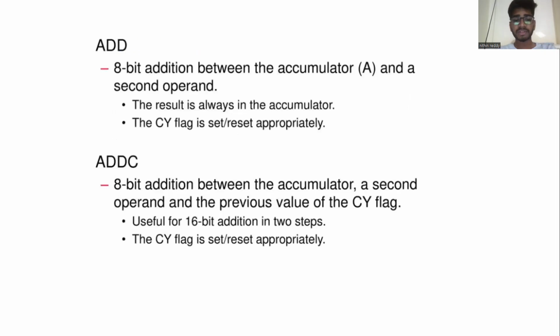And when coming to the features of 8051, the first ones are two 16-bit timers and four 8-bit ports, three internal and two external interrupts, one serial communication port, UART, and a bit as well as byte addressable RAM area of 16 bytes. 12 clock cycles constitute one machine cycle, and there are an 8-bit data bus and a 16-bit address bus.